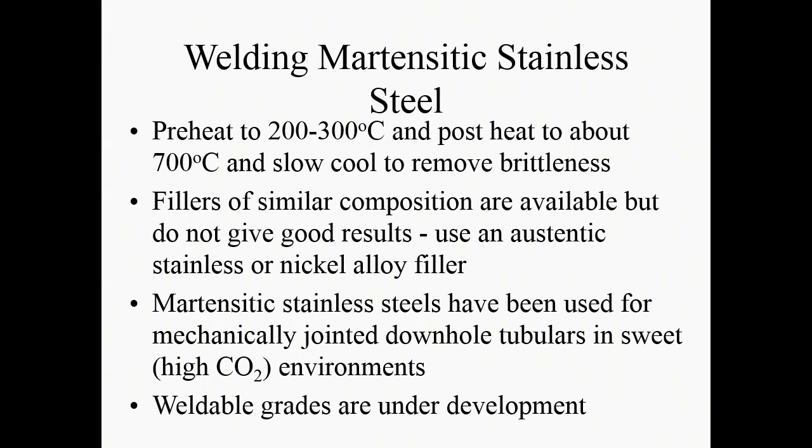As a welder, with a torch, going in to weld something at 300 degrees C is not nice. I can tell you from bitter experience, it's not something you want to do unless you actually have to. And it involves extra skill at being able to weld in that hot environment. You have to have heat protection as well as your normal welding gloves and things. So it's much more difficult to weld.